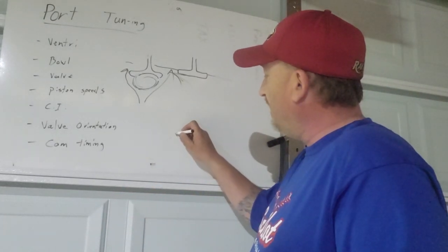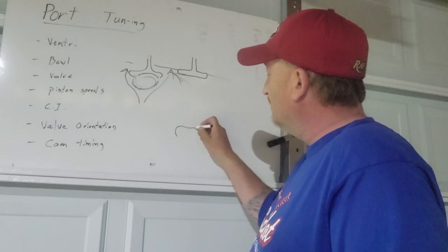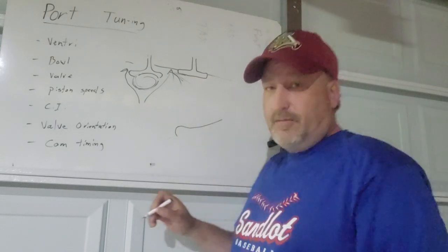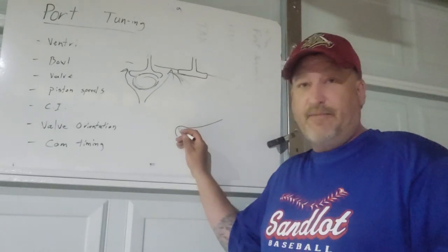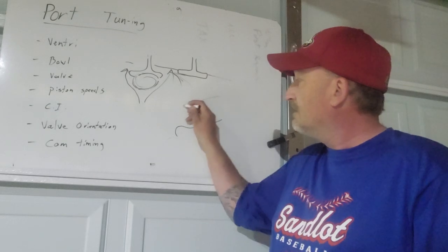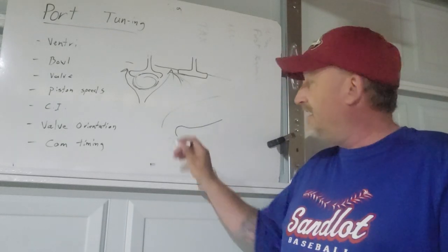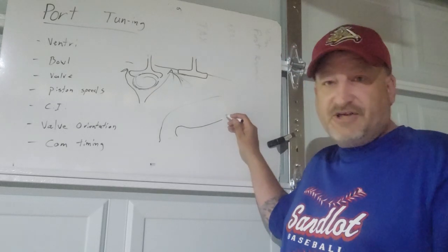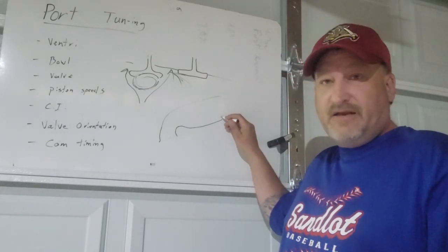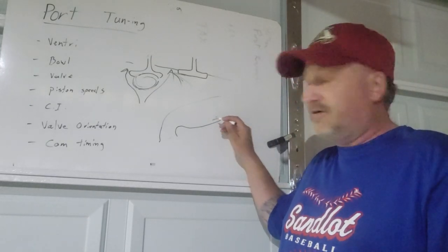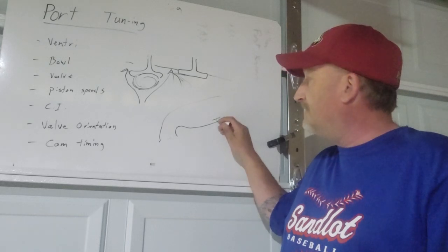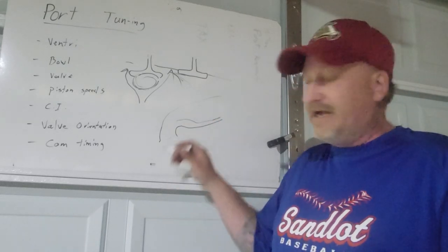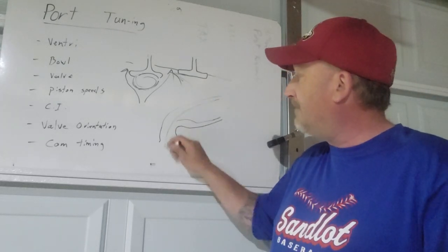Now, the short-turn radius of the small block Chevy includes that ramp. Once again, that ramp is there to initiate or to introduce more of those fuel molecules that have dropped out back into the high stream velocity area of the top of the port.